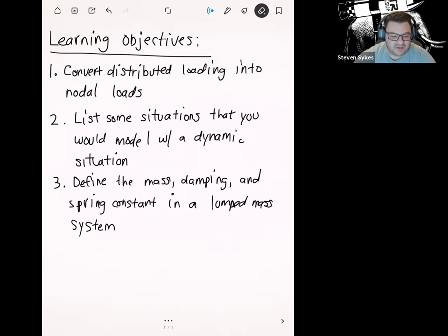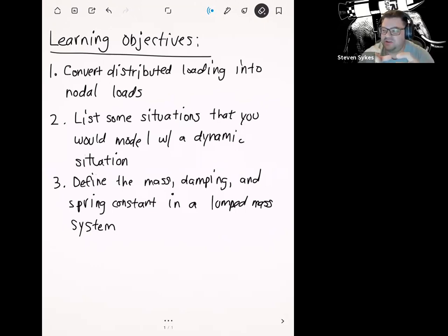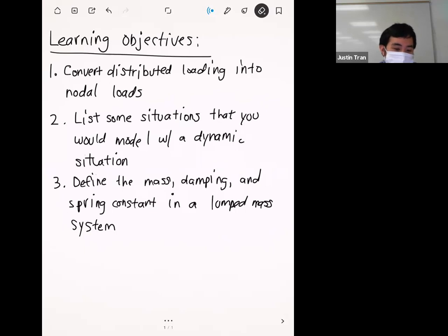The weird thing with MATLAB though is it keeps giving you these exponentially small numbers times 10 to the negative 16th or something like that. And I have to change in between format short and format short G or format bank in order to make sure the numbers come out a relatively small size. Oh yeah, that's one annoying thing. The reason for that is MATLAB solves those systems approximately, so they don't find a direct solution. And so sometimes you get something like that where it's off by machine precision, basically.